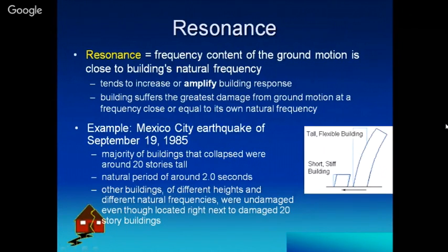It is not like that. It depends upon the frequency. At the place where the earthquake is occurring, the frequency content is high. So in the case of short period buildings where frequency is high, the frequency of the earthquake and the building will match and there will be a resonance, and it is going to create more damage to the shorter buildings generally.